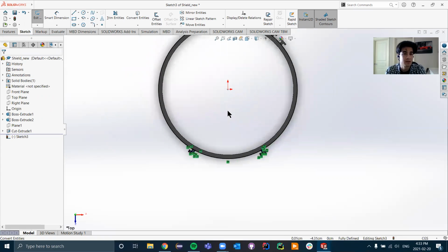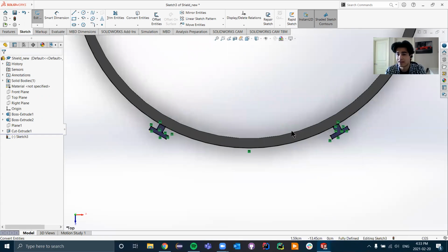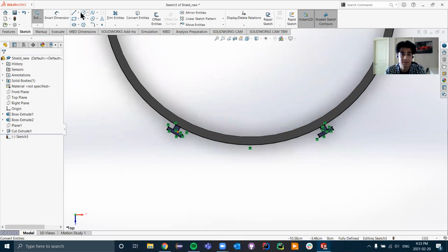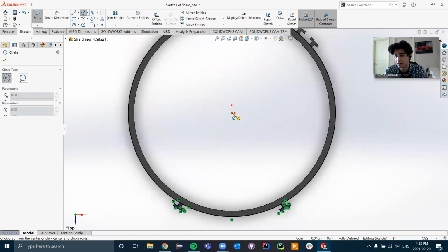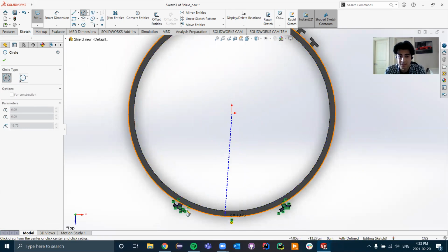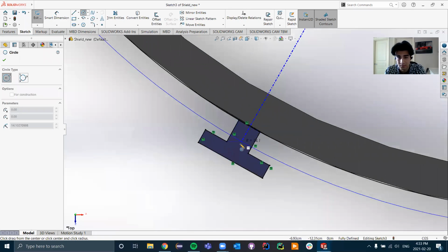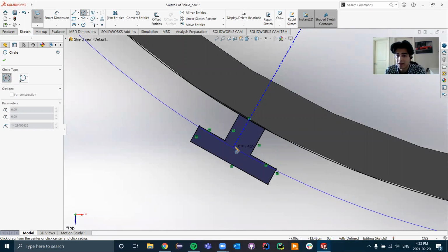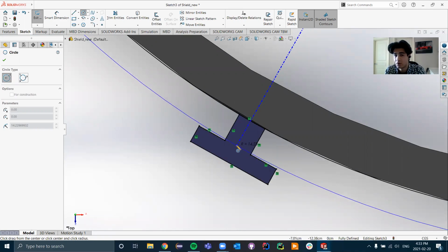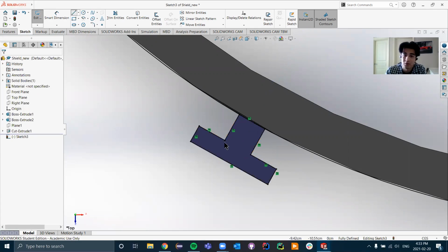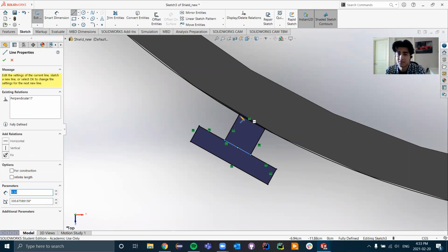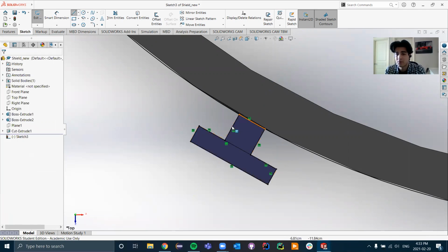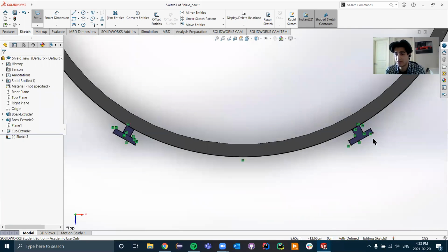That's the first part. Now the next part would be to actually create the connections that we desire for this. So using the origin of the previous circle, we already have our sketch origin placed conveniently here, so that's perfect. And essentially, I'm going to draw this out. And as you can see, we actually have nowhere to go off of. We have nowhere for this first band to actually fall within. And that can be fixed very quickly. We just draw a horizontal line across from here. Sorry, my computer's being a little bit slow today. I don't see why. We already have a horizontal line going across there, and we're going to do the same on the other contour as well.